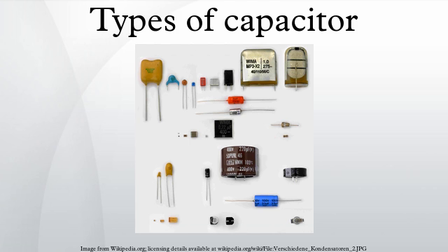Pulse current. The rated pulse load for a certain capacitor is limited by the rated voltage, the pulse repetition frequency, temperature range and pulse rise time. The pulse rise time represents the steepest voltage gradient of the pulse and is expressed in volts per microsecond. The rated pulse rise time is also indirectly the maximum capacity of an applicable peak current. The peak current is defined as I = C × dV/dt, where C is in microfarad.